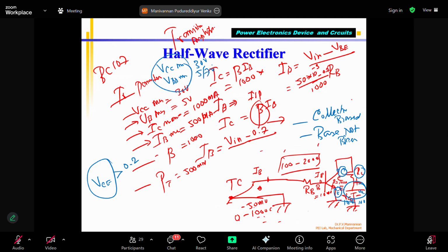If I supply a voltage within that range, and the base voltage VBB, or VB as some books say, is greater than 0.7 volts, I know that the base-emitter junction is forward bias. Then if the voltage between the collector and emitter, VCE, is greater than 0.2, I can say that my collector to emitter junction is biased. It is not forward bias. I say it is biased.